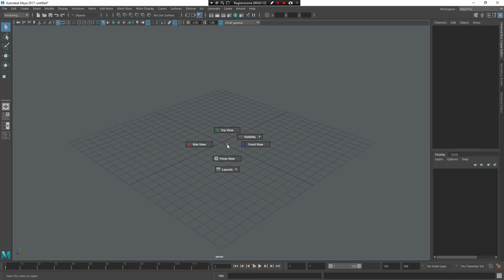Z and left mouse button, contextual marking menu, and Z and middle mouse button, universal marking menu for creating or managing Maya configuration or scene configuration, or if you want to work in some specific area like rigging, rendering, and animation. I think this is very easy. Only one key and two mouse buttons to press.